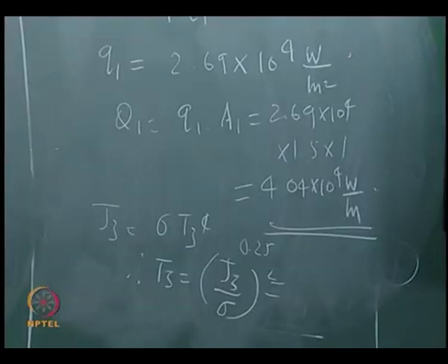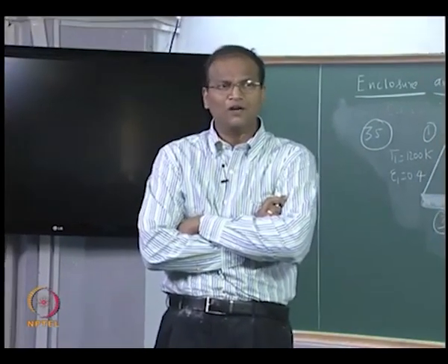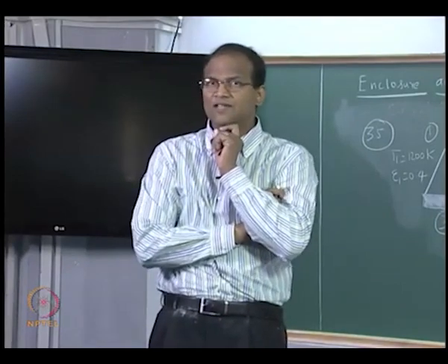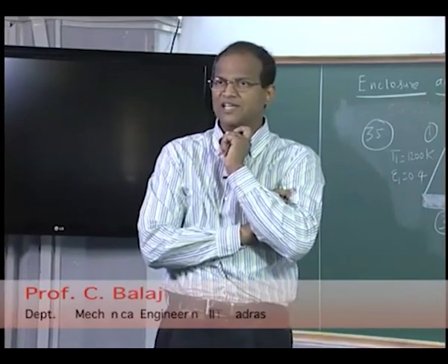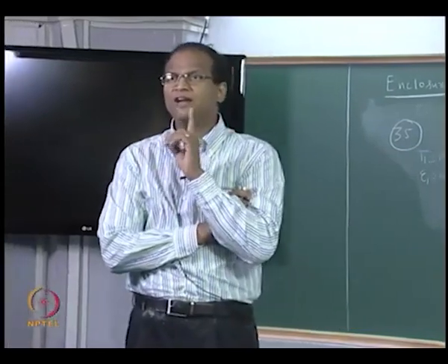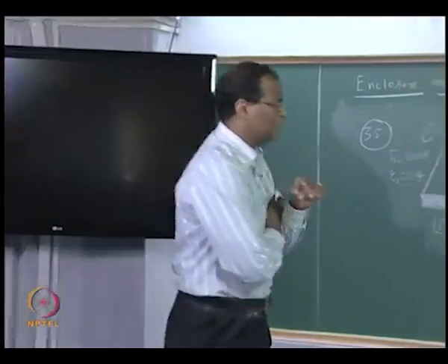We have already seen that J3 is equal to G3. I have worked out a formula specifically for the radiosity of a re-radiating surface, which is equivalent to that of a black body at that temperature. So the radiosity of that surface is independent of its emissivity. We have already proved this mathematically. So the answer must be between 800 and 1200. Any other answer is incorrect. 1010.7.